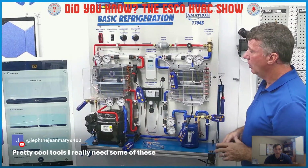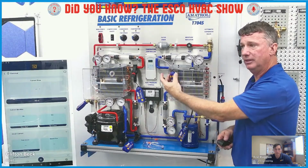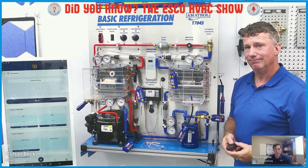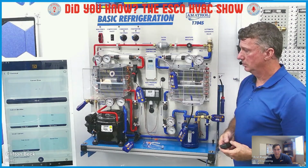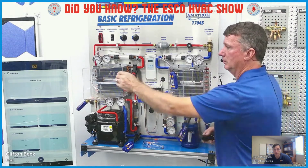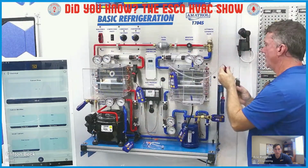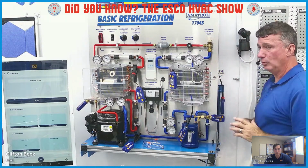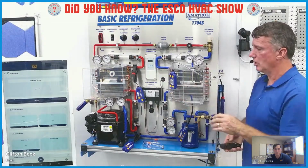Okay. So another item that you sent for us to be able to experiment with is the mano or the manometer, right? So we're taking our static pressures of the system, or looking for total static or pressure drop across specific components, whether it be coils or filters or the whole system. So I'm actually going to do the same with it. I'm going to bring it around so that we're going to be measuring pressure now on our airflow as well, so that we'll be measuring across the evaporator.